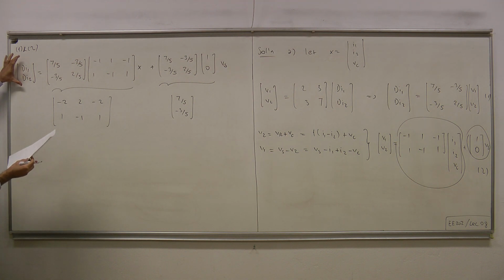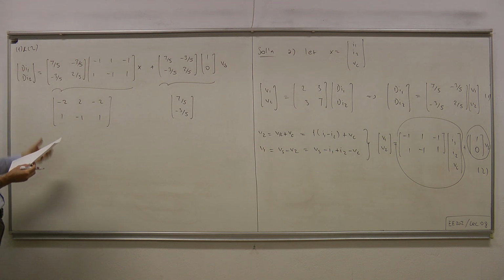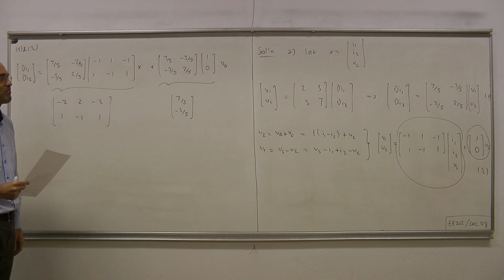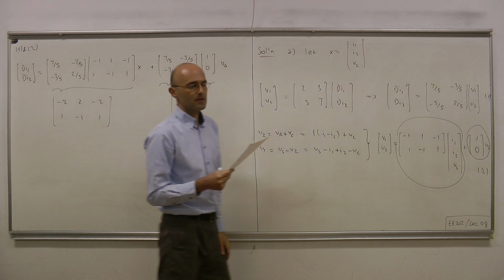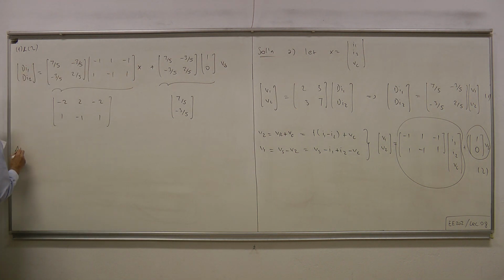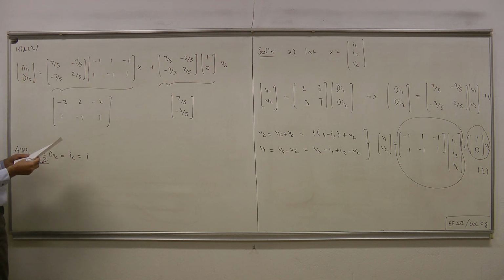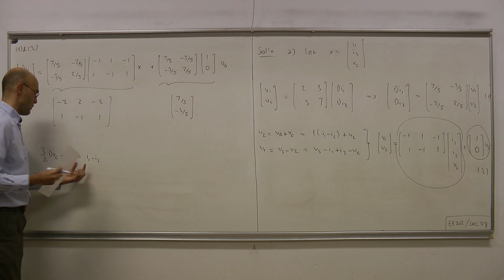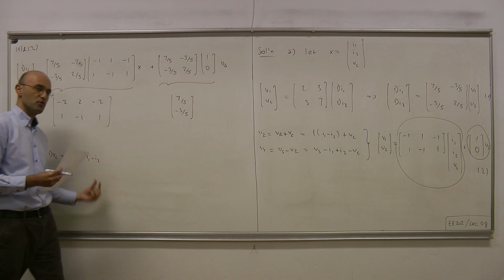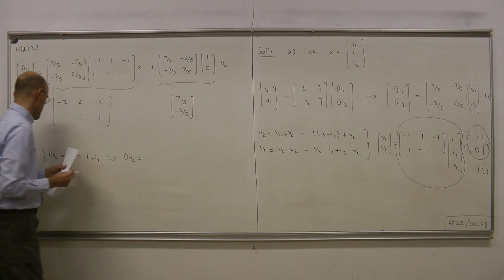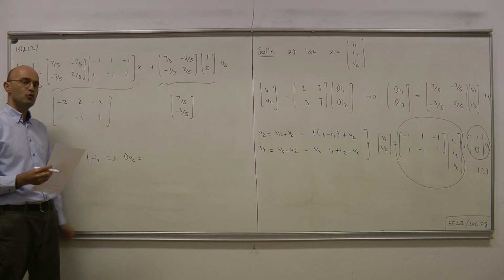Okay, so what we have is I1, I2 considered as a vector, dot, equals this thing times x plus this thing times Vs. Let's also figure out Vc dot. Also, 3 over 2 dVc. Okay, C dVc equals IC. And what's IC? IC is I1 minus I2. So we have been able to express it in terms of formulation variables. Therefore, dVc is 2 over 3 I1 minus 2 over 3 I2.